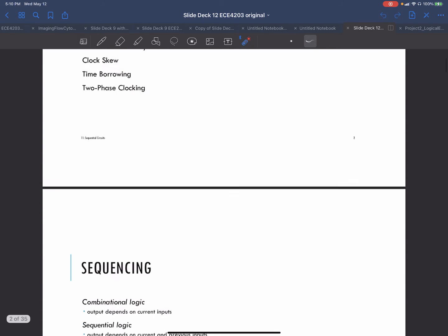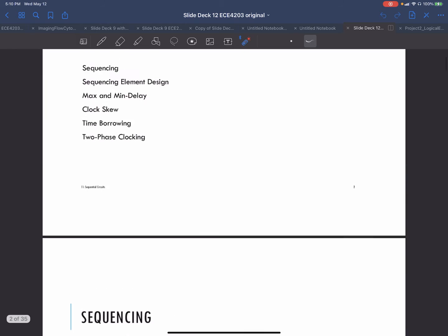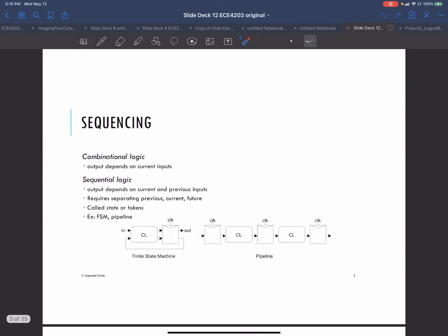Okay, guys, so we're going to talk about sequential circuits here. So far, we've been talking about combinational circuits. Combinational circuits are, I think of them as circuits that can't remember a previous state. Anything at their output is some combination of their immediate state. Let's say a NAND gate, depending on what A and B are, the output is just going to depend on the present state of A and B.